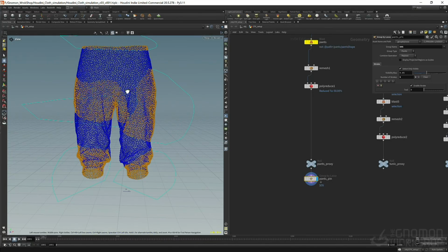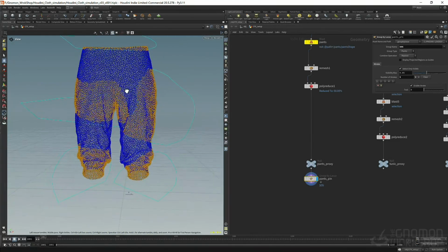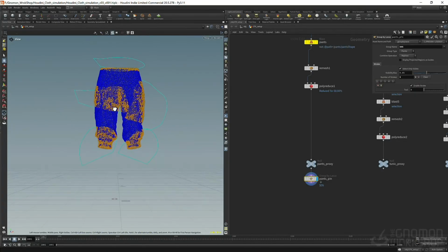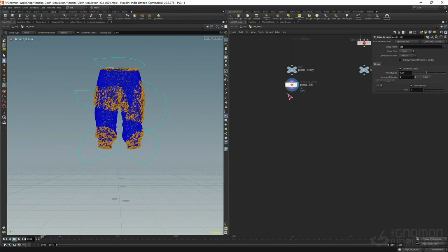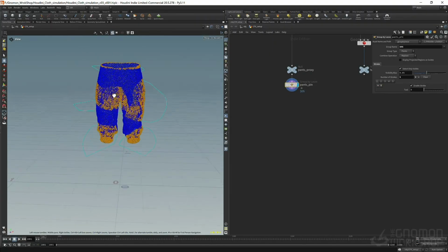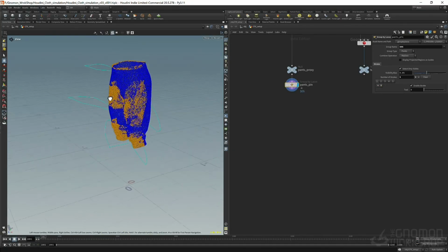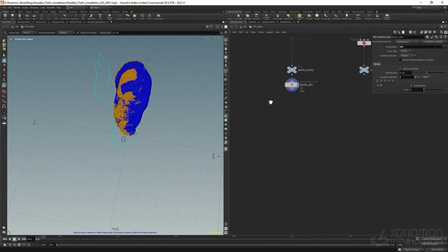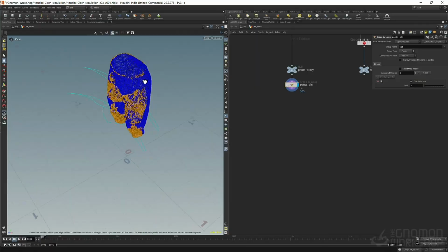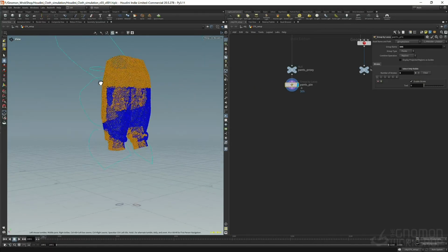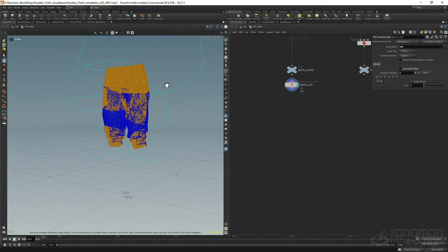So you can select more freely and have multiple curves at the same time. So with one node you can select multiple areas and you have an easier way to select. So it depends on which one you like. And also this is a select visible only. We can untick this, and if you select, it will select both sides.